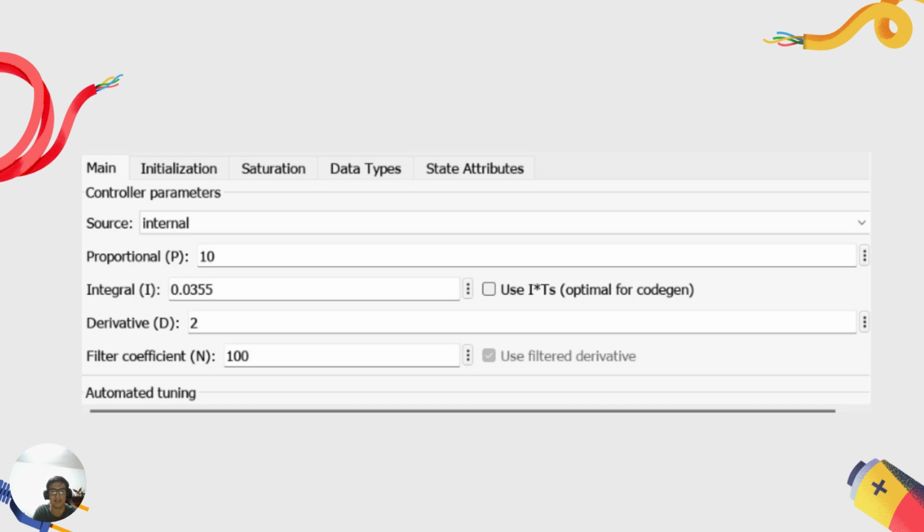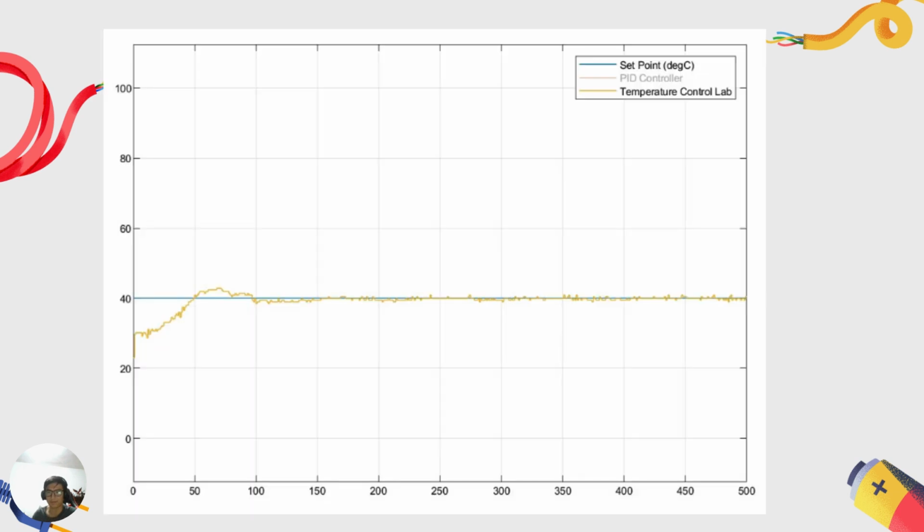We decided to choose a smaller value of Ki for speeding up the process, but not so small because the Ki parameter is the one in charge of reaching the stationary state error equal to 0. The proportional only helps, but the integral is responsible for this. And we also include the derivative at a moderate value of 2 for decreasing the overshoot and the settling time.